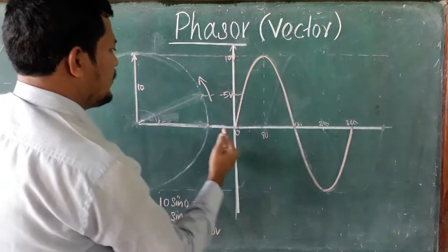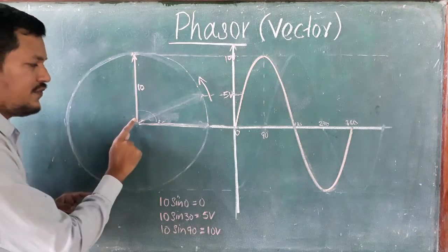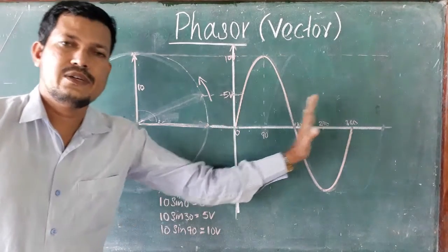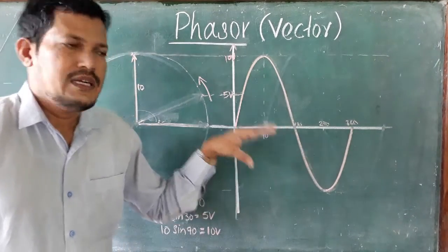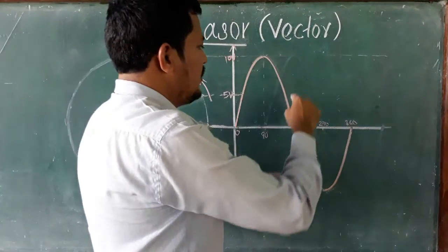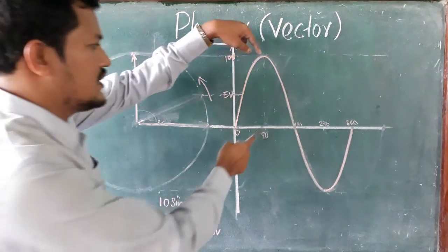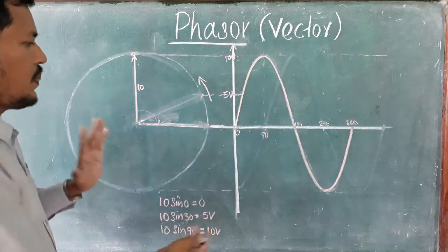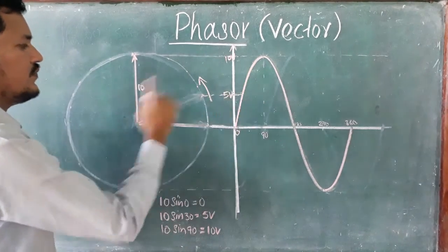We convert waveforms into phasor values and calculate with those. This covers addition, subtraction or division of two alternating quantities, or the total value at any point, or the potential difference between two alternating quantities, etc. For easy calculation only, we convert the alternating quantity into a phasor.